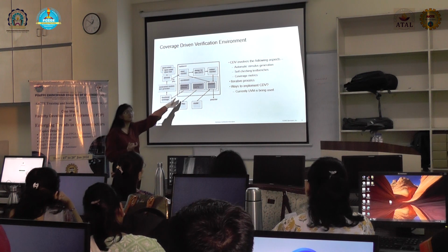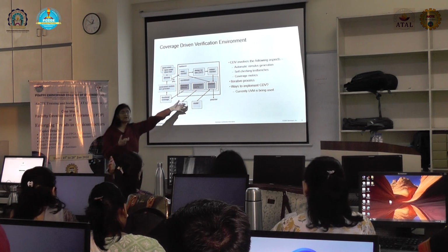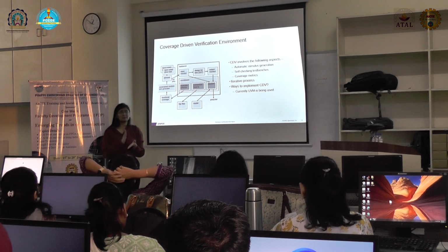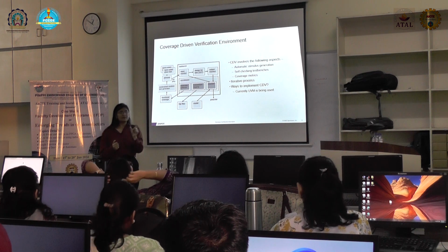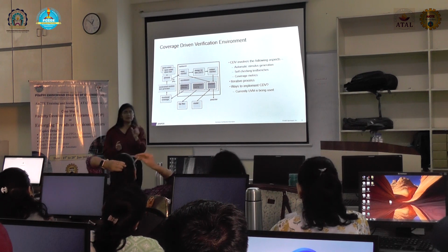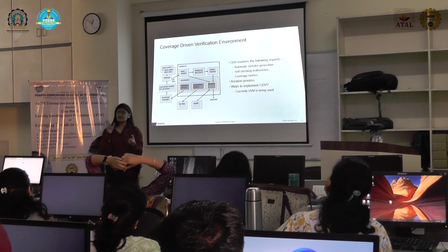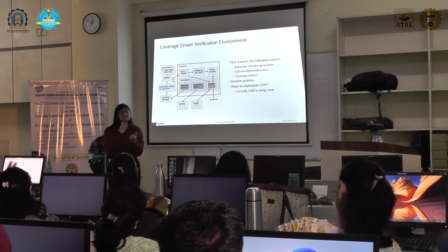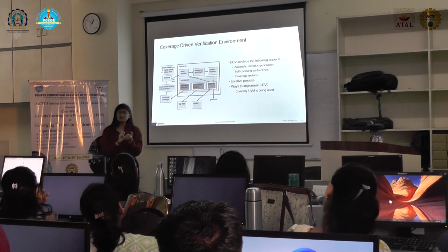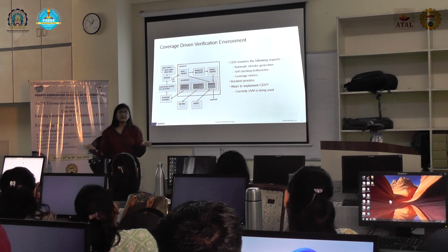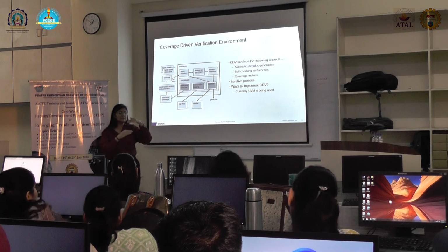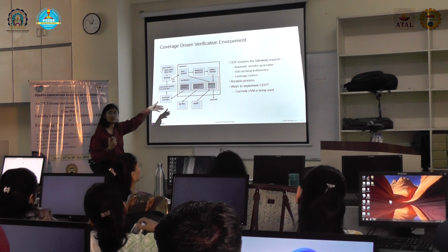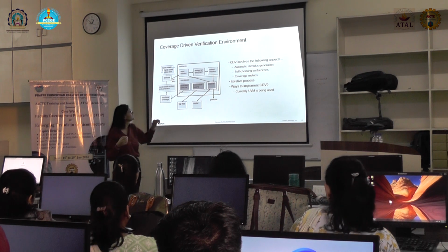And all these components are reusable components. Some components can be used in multiple ways. We had that example of master and slave. Let's say we have a driver, and we have a configuration to enable that driver. We can change the configuration and use that same driver as a master, and because we have a template, we can also use it as a slave. So reusability is increased by defining the same code in a different way. That has evolved from Verilog to SystemVerilog.